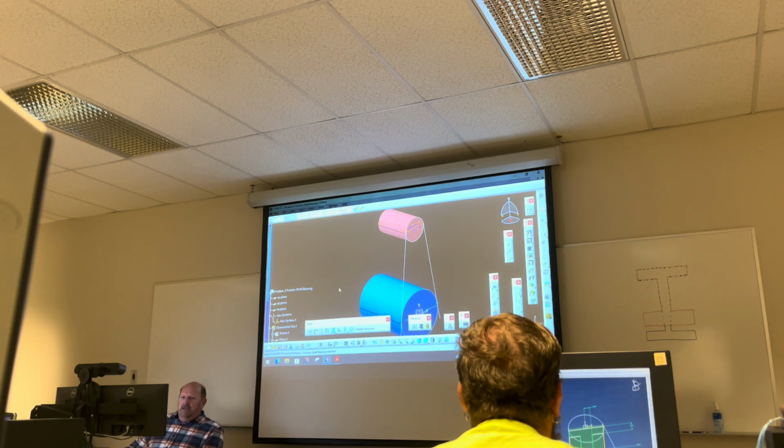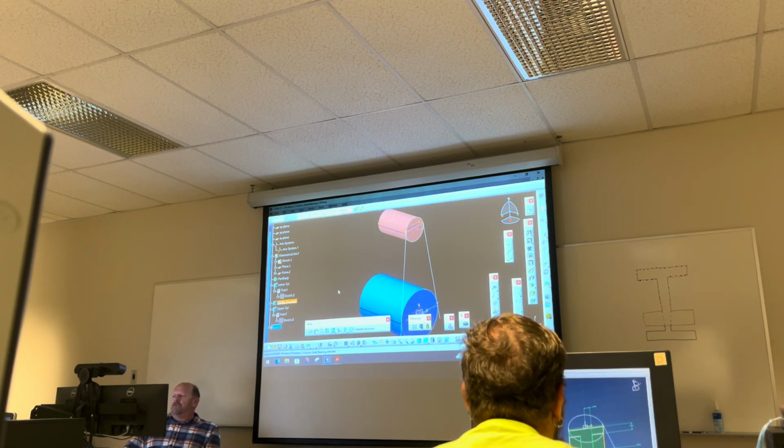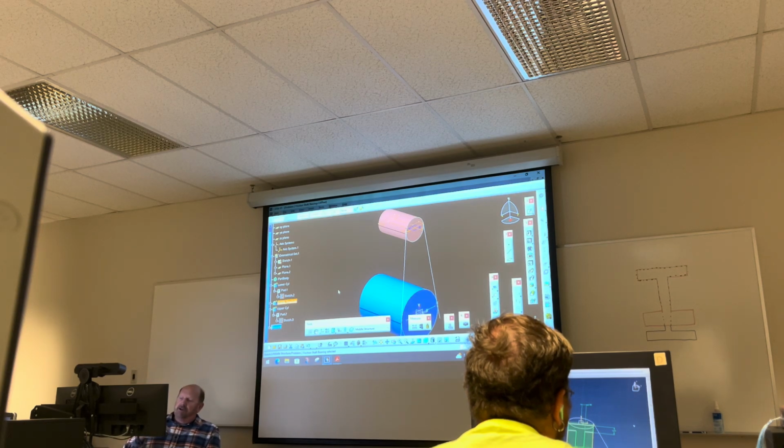Okay, and the reason I said middle structure here, when you do a multi-section solid, they don't need to be in separate bodies. You can put them in separate bodies. The issue is when you go to build it, if there's a sketch in another body, it will make a copy of it.